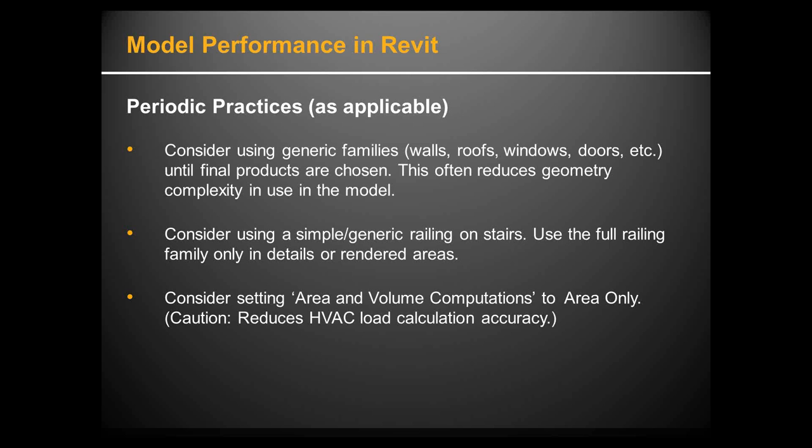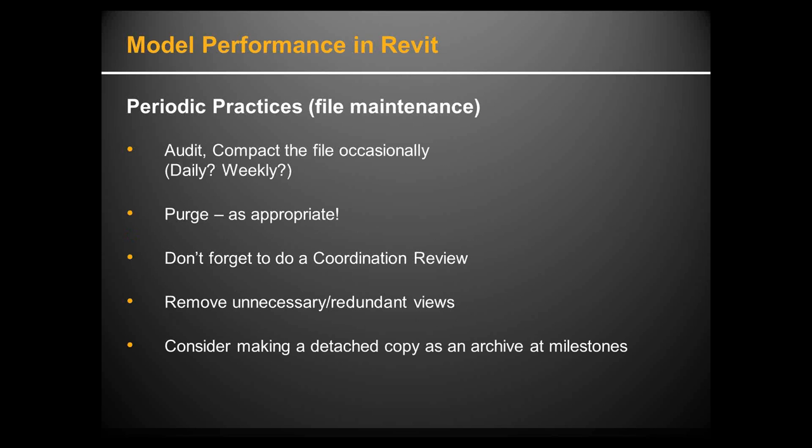All right, so we've got 3 questions here that we want to get to, and then we'll try to keep everybody on track. Basically, Teresa asks, is it true that hiding the 3D geometry in families and just creating symbolic lines on a plan and elevations helps open views faster? And we basically just answered this one. Yes, it does. It helps a lot. And that's a good best practice to get into, except when you need a view with that 3D thing in it.